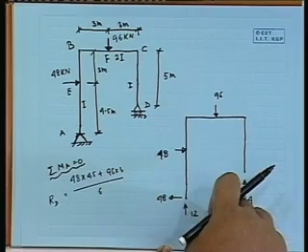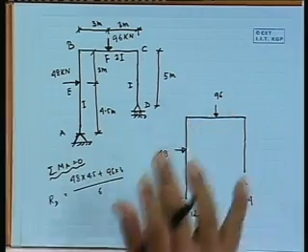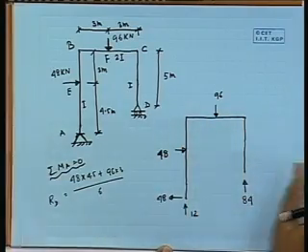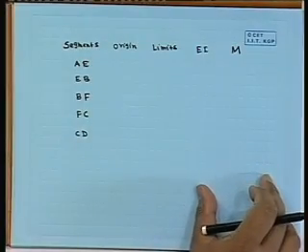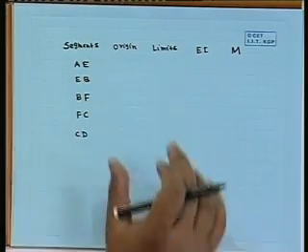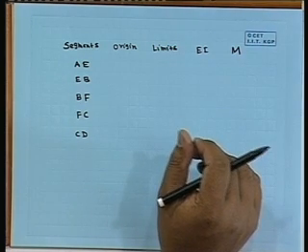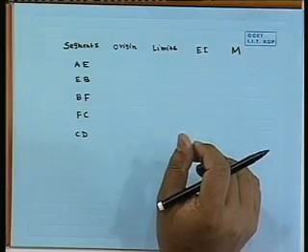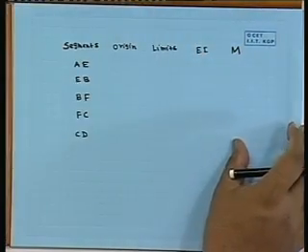Okay. So, this is the actual structure. We have removed the support and try to find out the reactions. The objective is we have to get the expression of capital M for the different segment. So, a reaction part we have determined. So, next job is for the different segment we have to find out the expression of capital M, and we may vary our original limits. I think with that we have to conclude today. We can try to solve it in the next class.